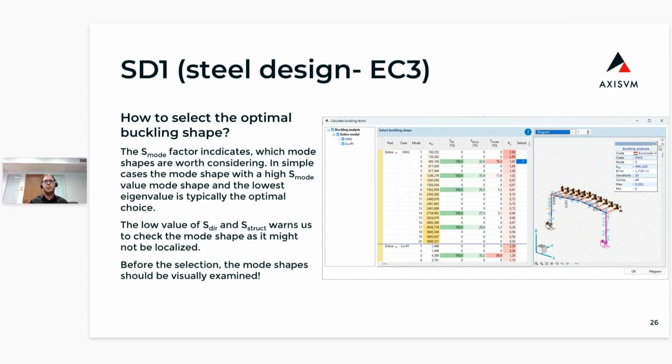You can run the buckling analysis based on different load cases or combinations and analyze either the entire model or a selected part of it. Once the analysis is complete, the program visualizes the result using green bar charts representing each sensitivity factor. This way, you are not just guessing based on visual shapes, you are working with reliable numerical indicators.